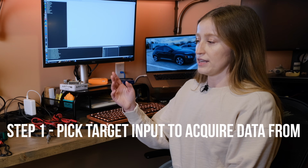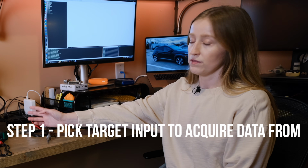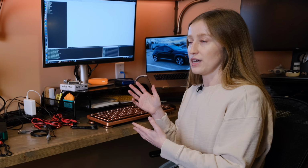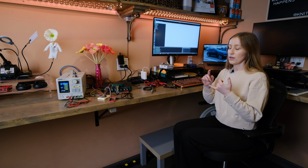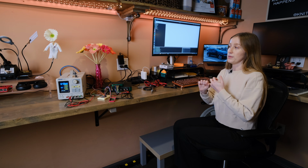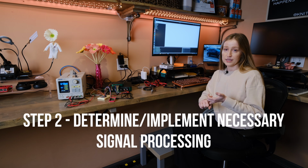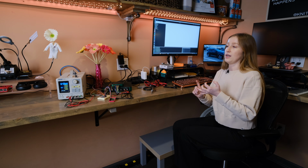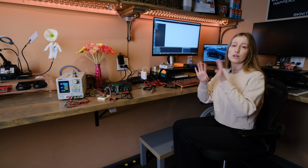Kind of the main idea of worksheet creation: there are 4 main steps in any worksheet you have. Pick your target input, whether that is some sort of digital device or one of the MCC computing devices. You need some sort of data input, because the overall goal of DASYLab is data acquisition. So pick your target hardware to acquire data from, then determine what you need to do to process that data, whether it's running it through a filter, checking to see when it reaches a threshold, all the various things.